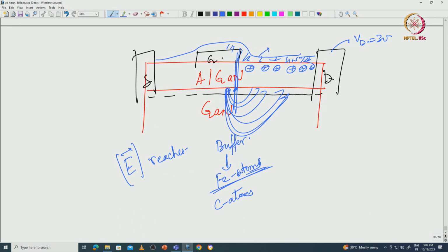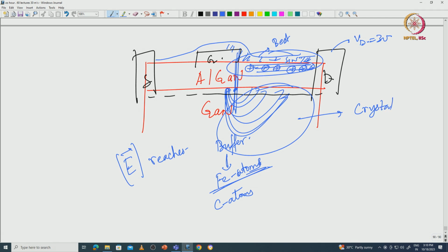Even if your silicon nitride is the best silicon nitride, the surface states are being taken care of, still the drain lag or the gate drain double pulsing, the collapse under that is a function of both the surface as well as the buffer. So, not only the surface has to be good, the buffer has to be good. By the buffer being good, it means the crystal quality has to be really good with as low dislocation, point defects, etc.